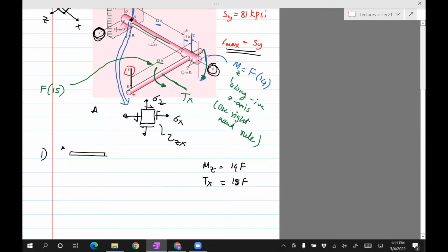So this is probably the most critical part. You need to do this just by using knowledge of statics, right? Force, distance cross force is the moment. And then you can think about it as no more moments which will come because of the way the force is applied. Okay, so now once we have those, we can ask, what does M induce?